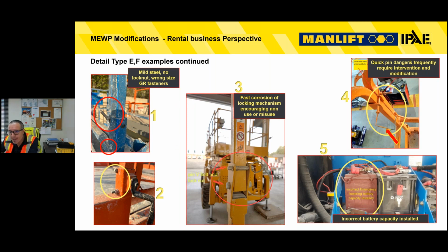And even I'm not a fan of these quick pins. You can see there's a quick pin here. I prefer the correct high tensile bolt with a nylock lock nut because these pins can fail. They can stay in the open position, and they're very easy to leave out there as well. So yeah, I prefer a proper lock nut with a high tensile bolt rather than these quick pins, and certainly using the correct bolt and nut, not this mild steel one here you can see.